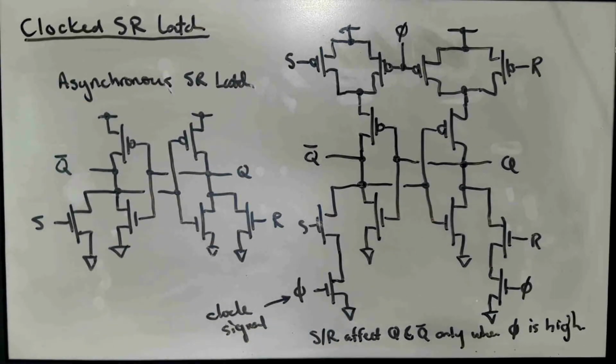Okay? So we don't often, in a context where we're building something like a register, work with SR latches. We typically will work with something called a D latch. And a D latch is one where S and R are strictly complementary to each other.